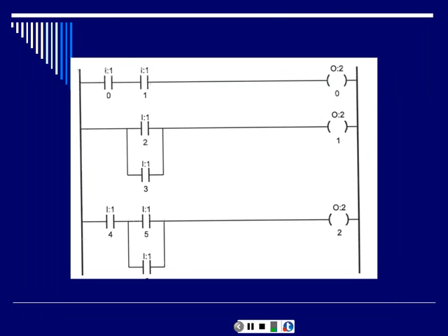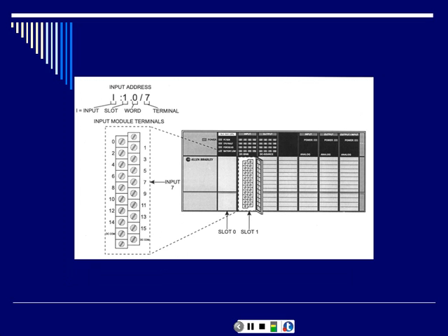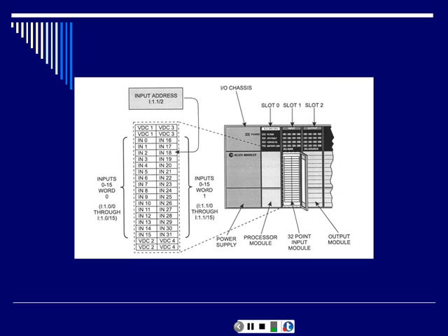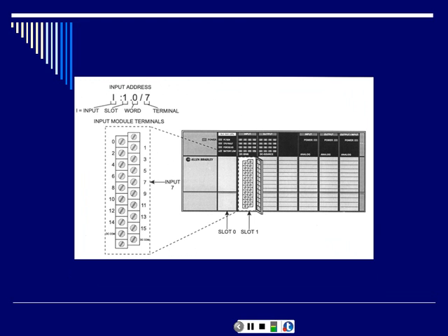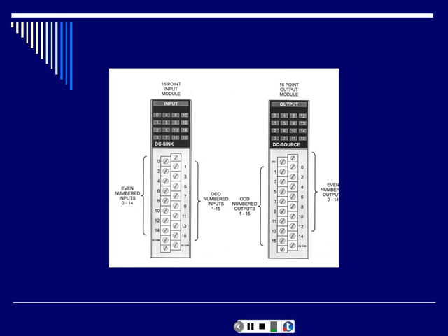With the output modules, now you'll have an output, okay? So it'll be an O. That's not a 0, it's an O for output. It would be in slot 2 because I have 0, 1, and here's my output, because this is all input. All my outputs are in 2. So 0, 2, and then that would be the first screw, so it would not be this one if this were the output module. It would be this one. Y'all with me? Okay, good deal.